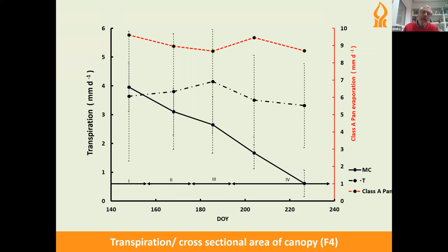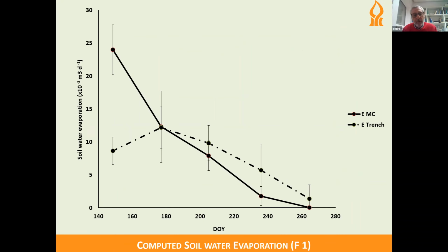But we see again what we saw for the previous water application, in the sense that the transpiration remains essentially constant, and the transpiration for the microcatchment decreases, in this case quite dramatically, to less than a quarter. We can calculate the actual evaporation rate from the data of evapotranspiration and transpiration, assuming that there is no drainage.